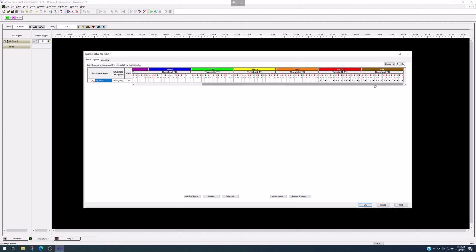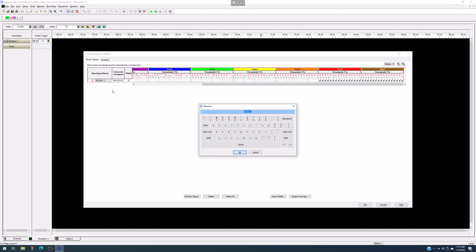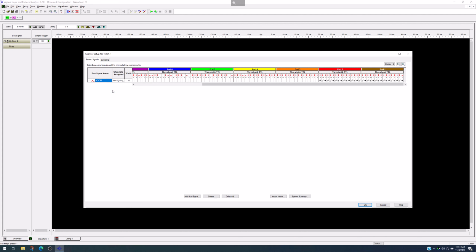So that little signal acquisition card that I plugged into my 386, I routed all of the address pins through that one little PCI Express connector. And so I'm going to come in here and say this is my address, ADDR, and these are the signals in this order. Pod 2, 15 down to 0 are going to be my highest word for my address. Pod 1 then will be my low word for my address. So that'll give me my 4 bytes or 32-bit address.